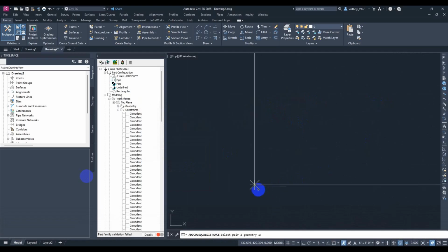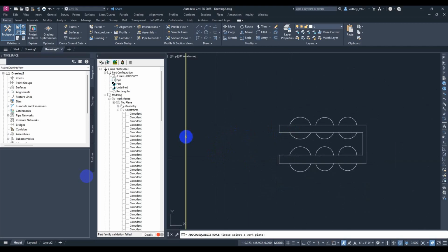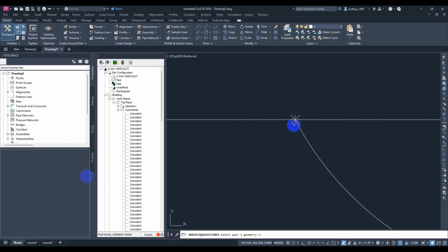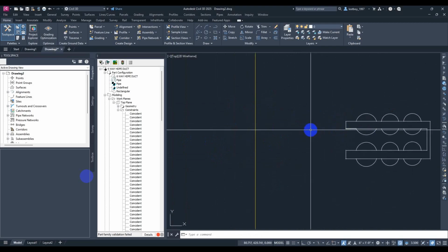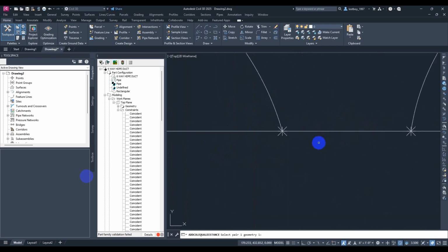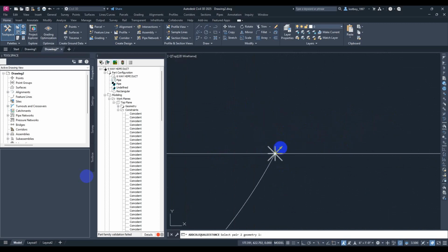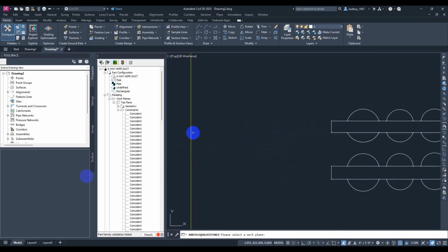And here we started with the equal distance. It's very important to make. So we can make sure that when we are giving one dimension, for example, between 2 points, this dimension will also be considered for the equal distances between the other points. So all will have the same value or move together. So this is very important.